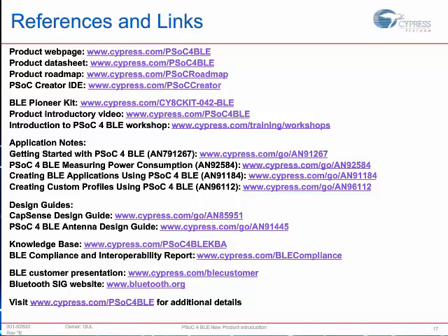Similarly, with the regulatory side of things, if you don't touch the antenna design and maintain it as is, you can reuse Cypress's FCC ID for regulatory certification on the wireless side of your design. There may be other portions of your system separate from this that may still need to go through FCC certification, which is fairly common for all consumer electronics sold in the USA. But the wireless part of it is greatly simplified because that is pre-certified and you can use Cypress's ID.